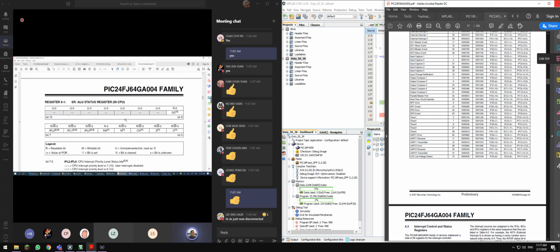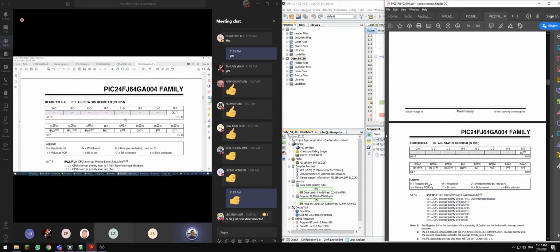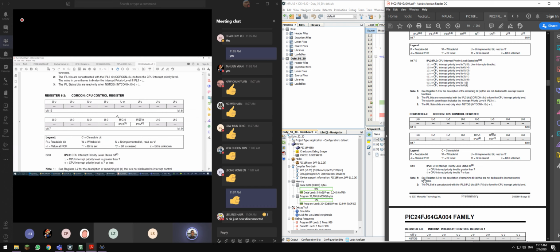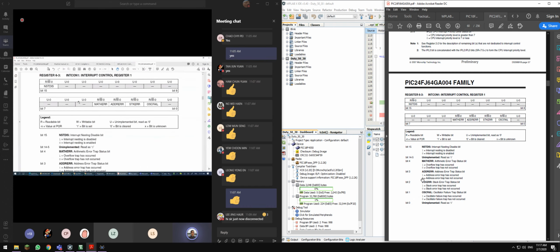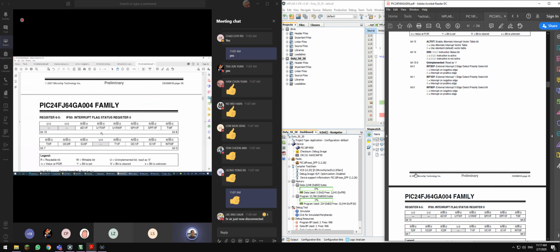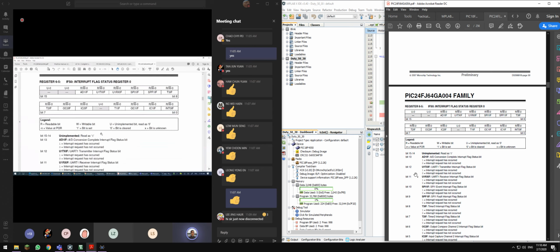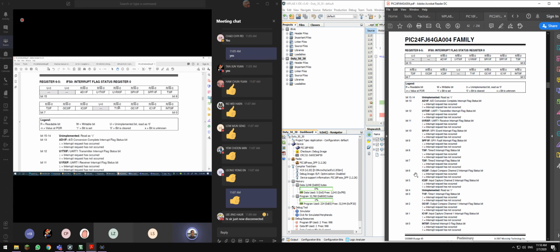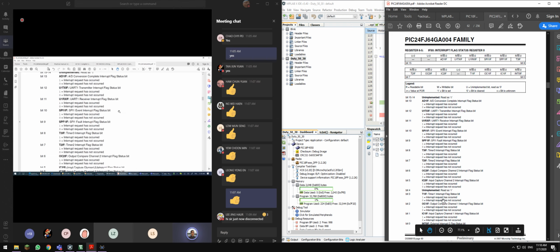So, class, they don't have a master enable, and they don't have high priority and low priority. Everything is predefined, so it's very straightforward. You just need to enable that particular bit only. For example, IFS0 involves the timer 1 interrupt flag, so remember just bit 0, 1, 2, 3. You have to enable this particular bit for the interrupt flag.